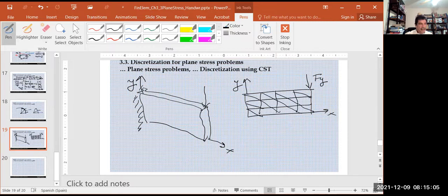Okay? And you can calculate, for example, the axial displacement of this point, the axial displacement of this, the axial displacement of that. If we follow the kinematic hypothesis, that's solid mechanics, bending of beams, then the axial displacement of these points must follow a straight line. In here, not necessarily, because we are not assuming the kinematic hypothesis. So that's why this example is so interesting.